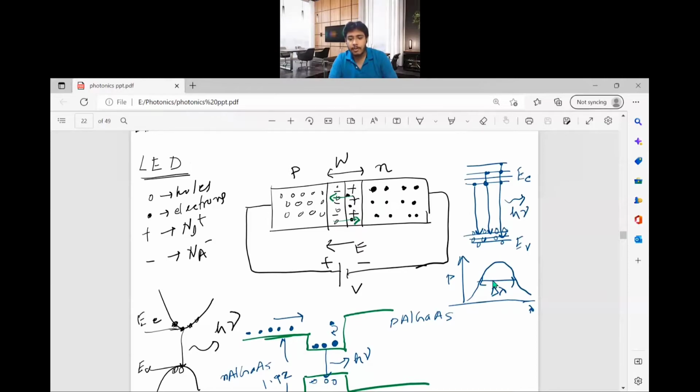Whereas for a laser, you have a narrow band spectrum, where the deviation from the center frequency is very small. For the LED, the deviation is very broad. So in a normal PN junction diode, the spectrum is more broad because this spontaneous emission is not in your control, and also they can recombine in other regions.